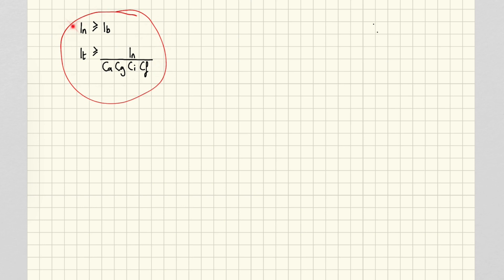So although this might look complicated, in order to find most of these values, it's either what size device you are fitting, or they are known values taken from BS7671. What might this look like then? Well, if we've got a design current, an IB, which is 32 amps, then our IN, which is, remember, our protective device, so the device we're going to install, well, 32 is a fairly common size, so we can fit a 32 amp in there.